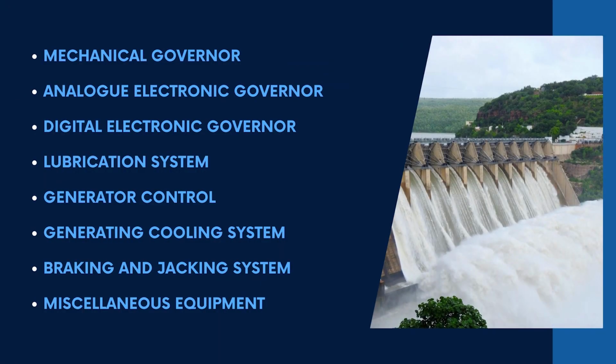Now, let us have a look at generator cooling systems. Generator cooling involves air circulation by rotor fans. Generators are usually ventilated on a closed system in which the same air is continuously recirculated and passes through the water cooling units. The water supply for both oil and air coolers can readily be drawn from the turbine casing through reducing valves and strainers, so that it flows automatically when the main inlet valves are open.